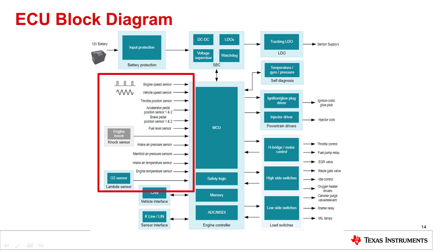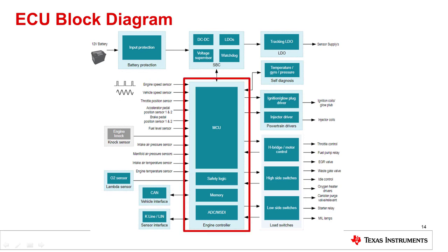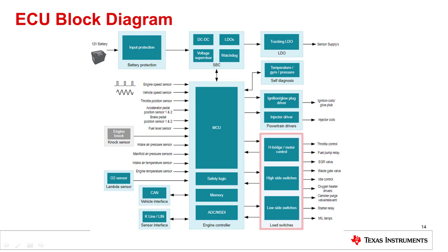A variety of input sensors are used to manage the performance of the engine when it is running. Parameters like temperature, pressure, position, exhaust, torque, and current must be monitored using dedicated sensors. These sensors send electrical signals to the ECU that can calculate its current performance versus its ideal performance. This is done by comparing the current performance values to internal lookup tables in the ECU to determine the adjustments needed in the system. Finally, to adjust to the ideal performance, the ECU sends signals to the outputs in the system to control the parameters needed. We will discuss these in detail later.